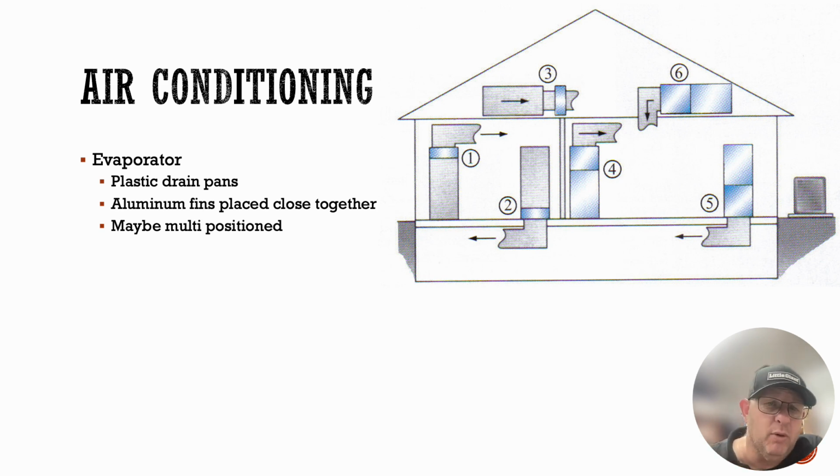Now, furnace number 1 and furnace number 2 basically have an H coil that's sitting on top of them. 1, 2, and 3 all have H coils, and you can see the different ways that we can use that coil to be placed on the furnace itself. This is an upflow furnace, number 1. Number 2 happens to be a counterflow furnace, and then number 3 happens to be a discharge right or horizontal right application for an air handler or a furnace that we're going to be placing within this individual's house.